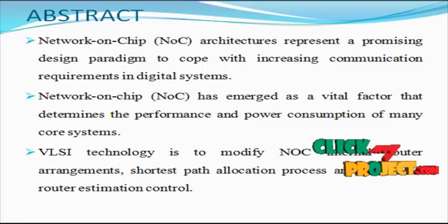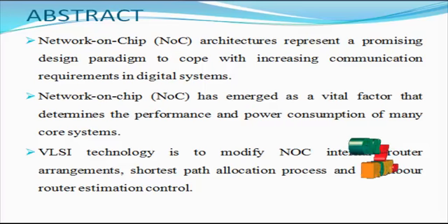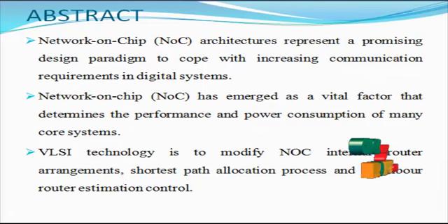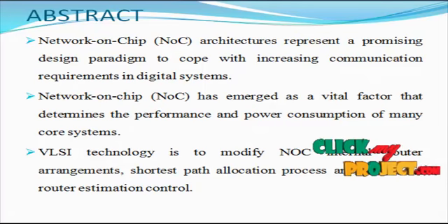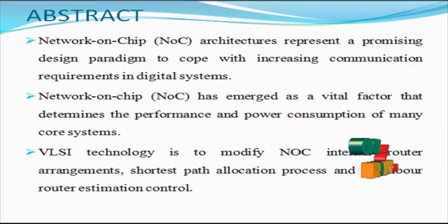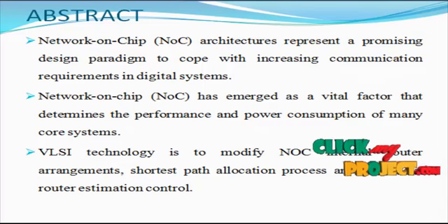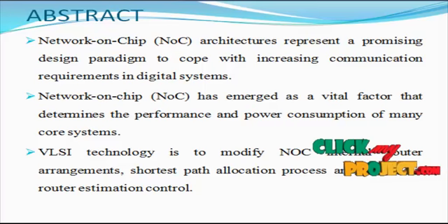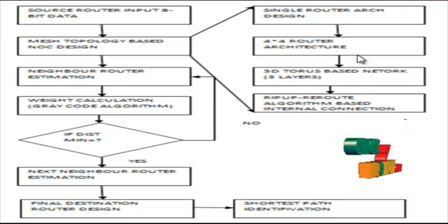In addition, we evaluate the 3D Torus system with synthetic traffic, uniform and transpose patterns, and real parallel multi-thread benchmarks, comparing with 3D mesh. Our experimental results demonstrated a significant reduction in the average packet latency and high throughput, as well as major improvement in execution cycles in typical thermal-aware IP mapping methods in 3D Torus multi-core systems.